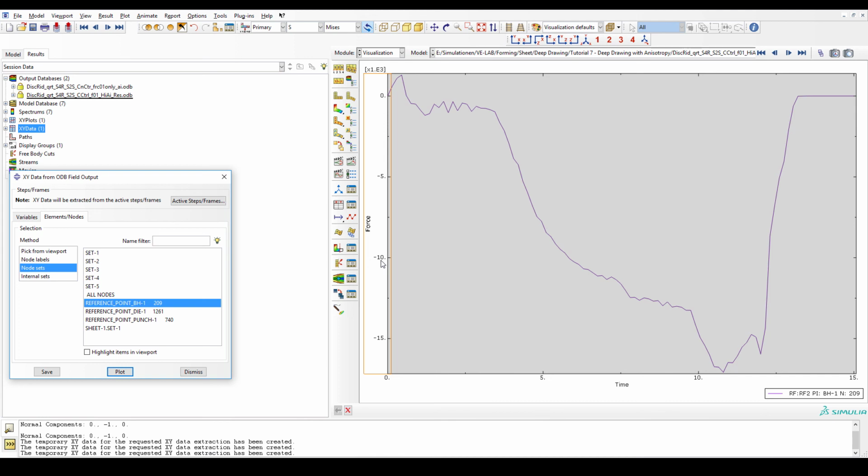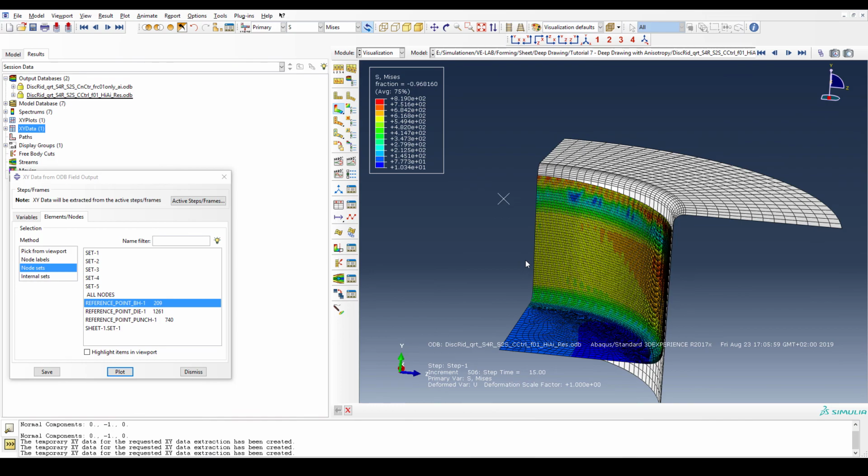I would really like to think about trying out in an actual machine a non-constant function over time for the blank holder force, and see how this might affect my results. Because if the area underneath the blank holder gets smaller, we talked about this, right? The actual contact pressure is increased if you give the same force to the blank holder all the time.